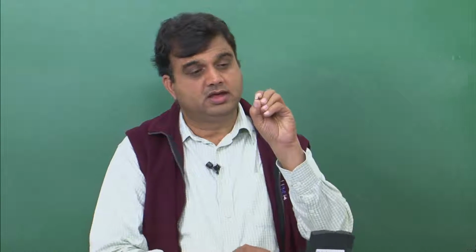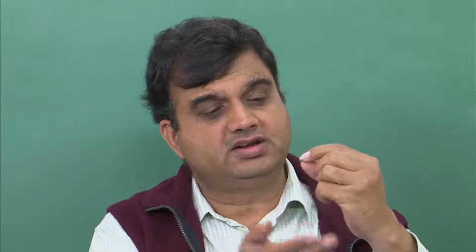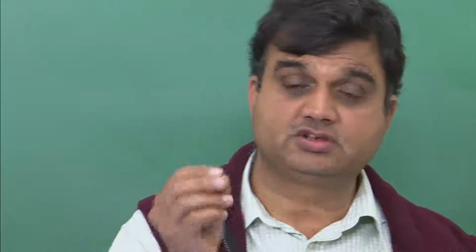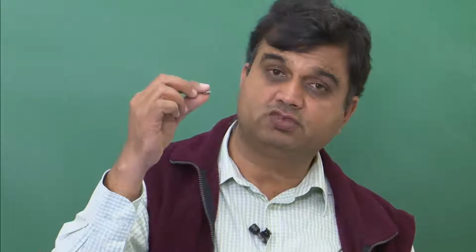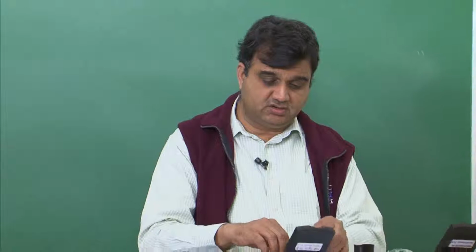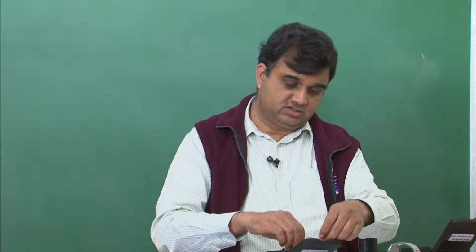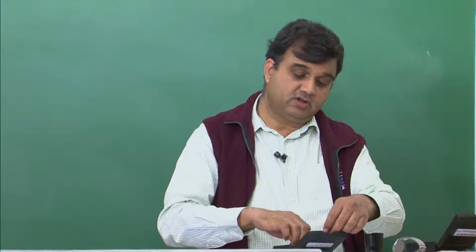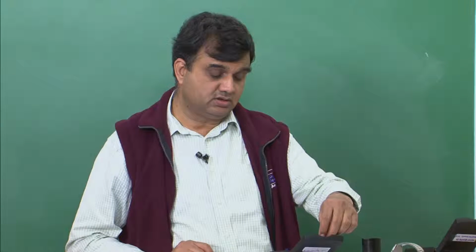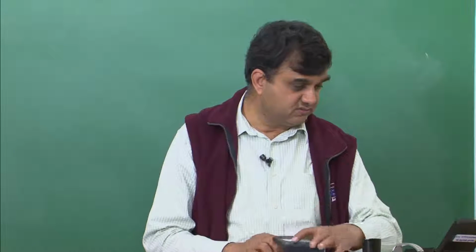So this is one microphone, and you can see it from this side also. It's 1/4 of an inch, so it's about 6 millimeters in diameter. I am just trying to show you different topologies of microphones that are available. This may not be the most comprehensive set of shapes, but I wanted to give you some idea. Here the microphone is separate, and I have to connect it with a preamplifier so that I can use it successfully. Looking at the sensitivity of this microphone, it says its sensitivity is minus 48.1 decibels, with the reference being 1 volt per Pascal. So this is one microphone.